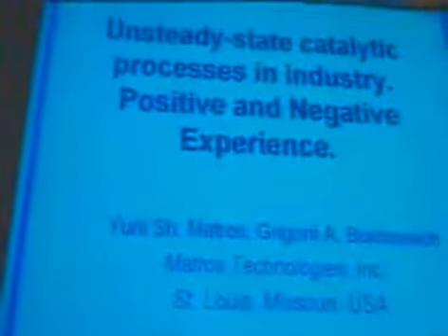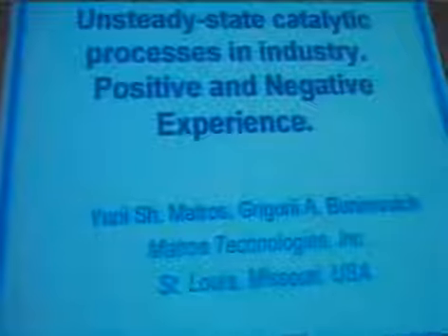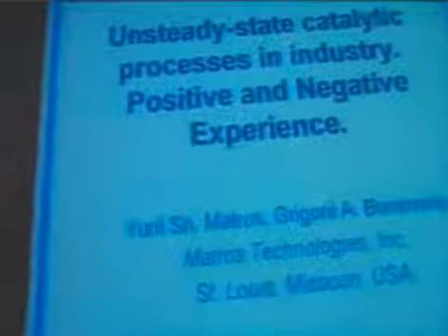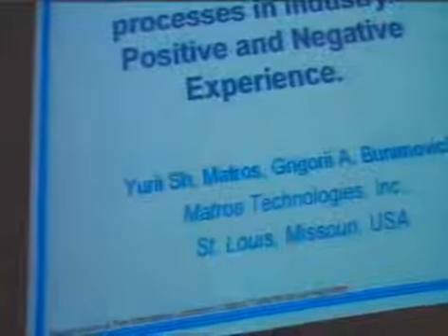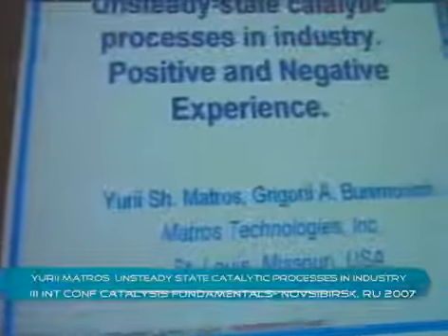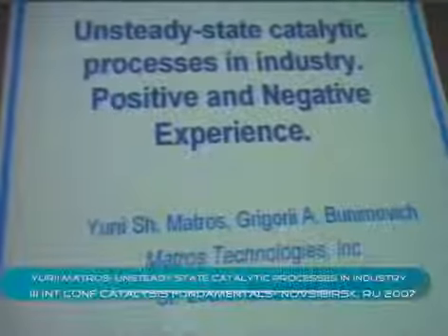The main difference between reactors operating in forced unsteady state conditions and steady state conditions is that we are trying to change some input parameters like temperature, concentration, the direction of the flow rate to initiate conditions inside the reactor unacceptable for steady state conditions. We are trying to construct the field of the state of the catalyst, temperature profiles, concentration profiles more acceptable from the point of view of high selectivity and more productivity. This is the big difference from processes realizing steady state conditions.